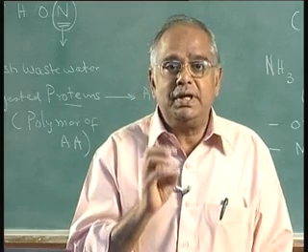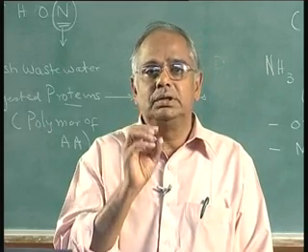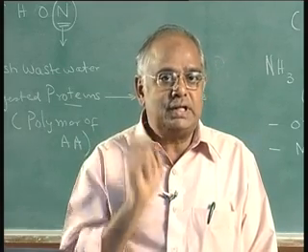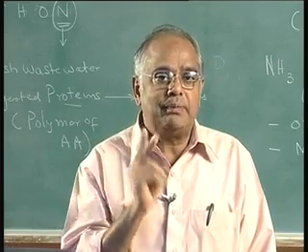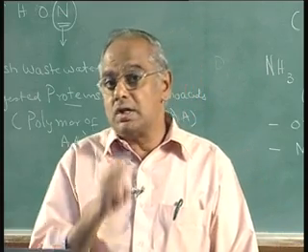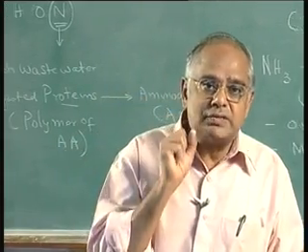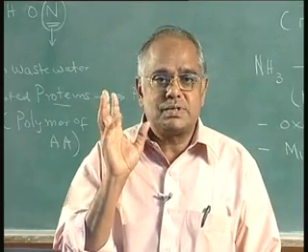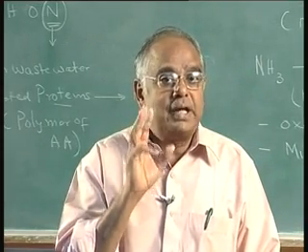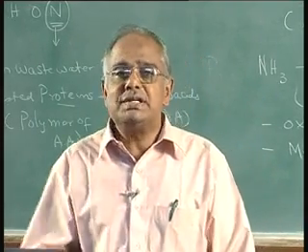Primary and secondary treatment remove, number one, the suspended solids, and number two, the organic matter present in the wastewater, and we also disinfect it to kill the microorganisms. That is the primary and secondary treatment, while tertiary is optional.